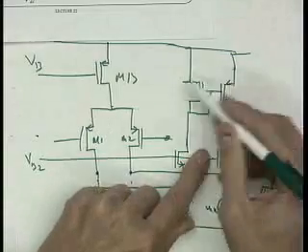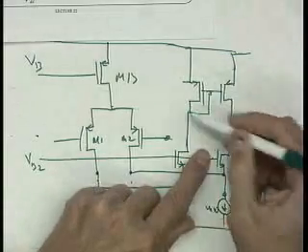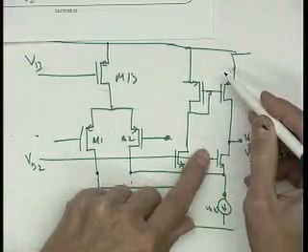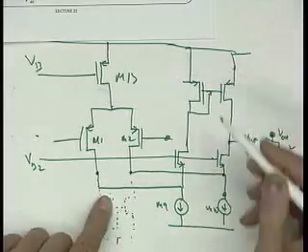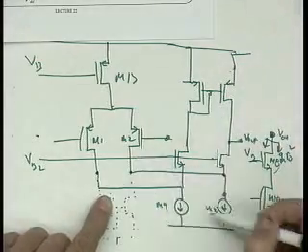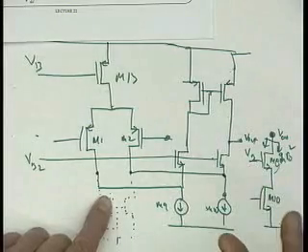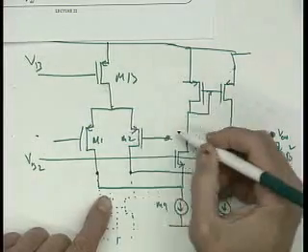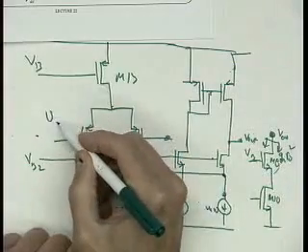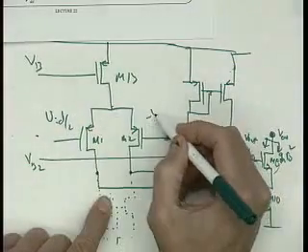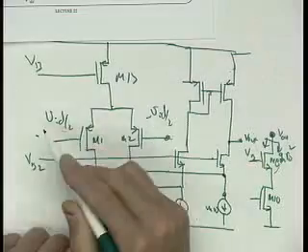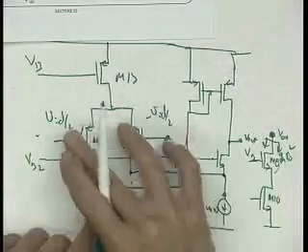So here's our good old uncascoded current source load. So now, how does this folding work? Here's the really tricky part, okay? If we put in a differential input across this, let's make it pure differential, Vn differential over 2 minus Vn differential over 2 on this one.